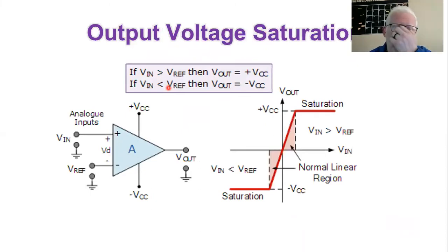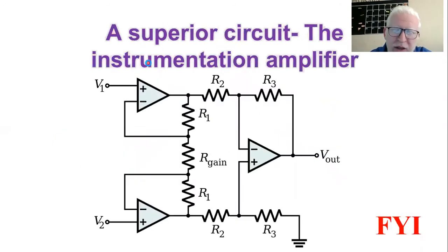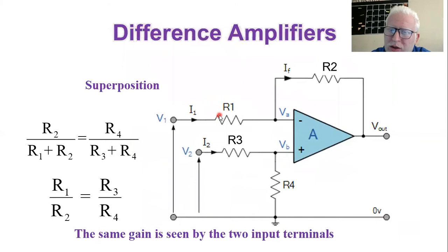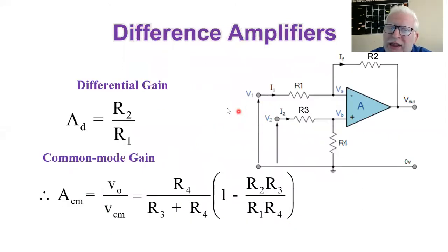Another question I proposed maybe at the end of the previous lecture, if you remember, my dear students, is why we are using a closed loop circuit in order to demonstrate a difference amplifier. The question is very simple. Here in this circuit, we have two inputs, and the output is R2 over R1 times V2 minus V1, which is the differential input, if you remember.